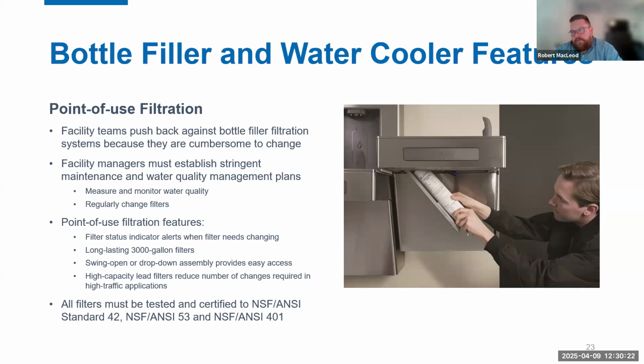the filters themselves will be certified to the NSF 401 standard, but part of that standard is a volume rating of 3,000 gallons or 1 year. So 1 year is typically about the max that you'd ever want with what NSF recommends. You're going to be changing that filter annually at least. But again, in super high traffic areas, you may be changing that, as you said, every 6 months. Certainly could happen that way as well.